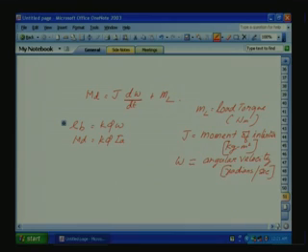So, from these two relations we can bring in the speed into our original equation, because the speed is our output, input is the armature voltage. So, we should have a relation between these two. How to find out? Now, let us take the previous equation, armature voltage equation, that also we will write here for clarity, so that again we can refer to it.